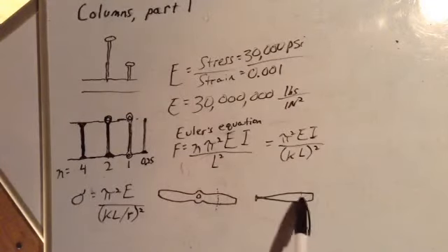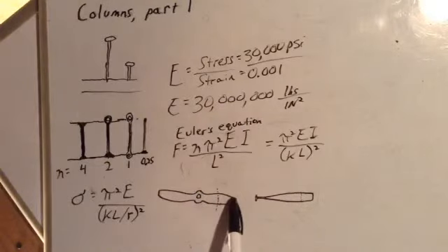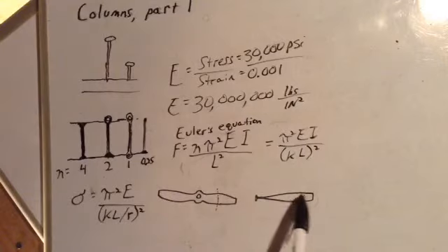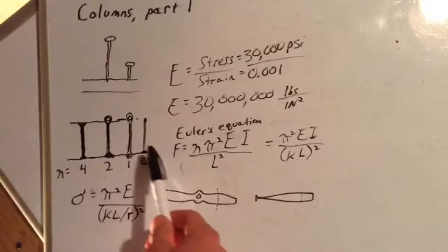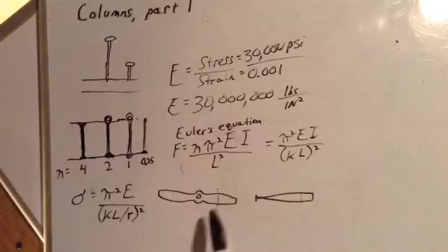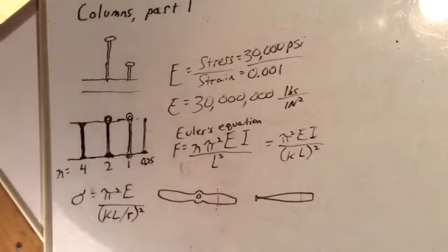is at about 55% of the way from the center of a propeller to the tip, but it would be closer to the right end of a baseball bat because the propeller is massive in the center and thin at the tip, whereas a baseball bat's just the opposite. It's more massive toward the right end. Now, the radius of gyration of a cross-section of a beam would be the area radius of gyration. The radius of gyration of a propeller or a bat would be a mass radius of gyration.